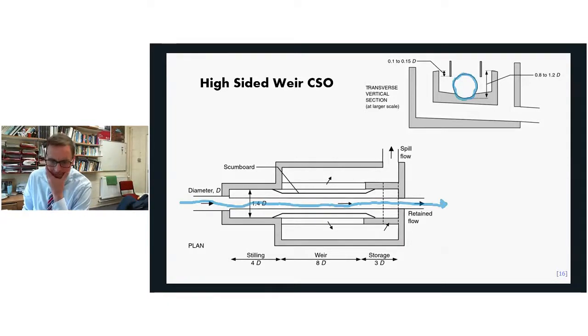Now in the midsection, the pipe isn't wholly formed. The pipe will just be the lower section, as you can see. If you look at the top right, between those 2 points there, you've really just got the invert of the pipe, and the rest of it then goes into the square channel, which you can see. Square channel with a sloped bottom.